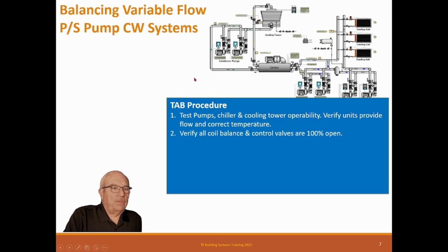Verify all coil balance and control valves are 100% open. So now on all the coils, you've got a control valve and you've got a balance valve. You need to command open the control valves, command them open to 100%, and leave them there, lock them there. And then the balance valves, you need to manually check that they're all 100% open. Just like an air system, same problem. Gotta make sure they're open.